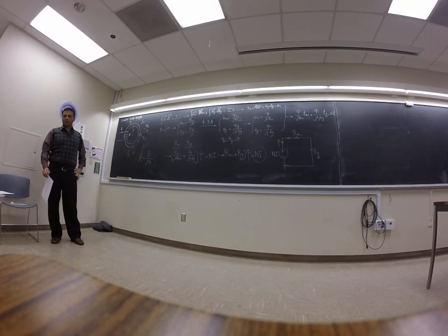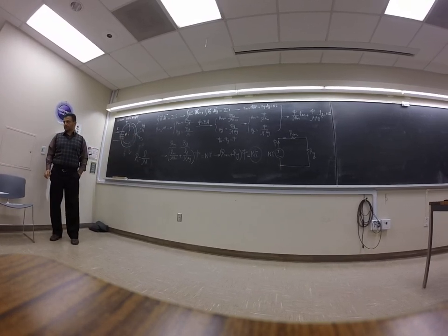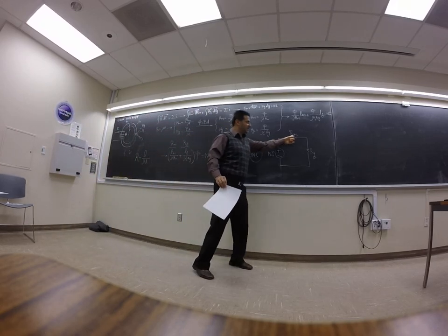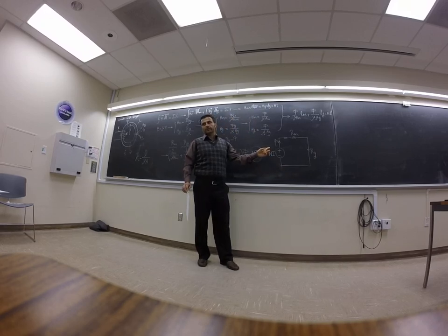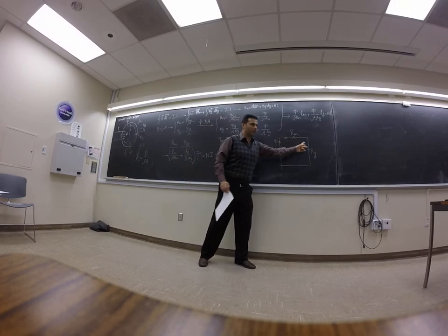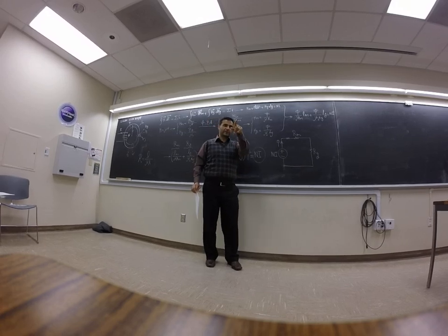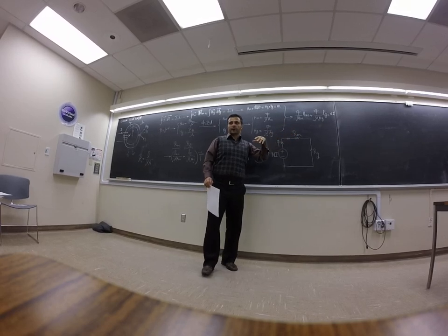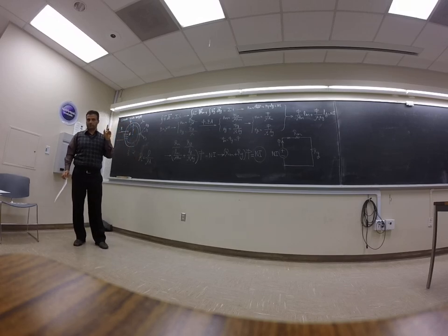Now, I want to talk about one more thing. Why I called here Ag? Because I want to talk about that one. See, flux. Look at here. Flux everywhere is the same. Is the H the same or not? Is it going to be H the same for all of them? No. Why? Permeability is different, exactly. For the magnetic part, permeability is something, and for the non-magnetic parts is something else. That's the main reason, because they have different mu, right?